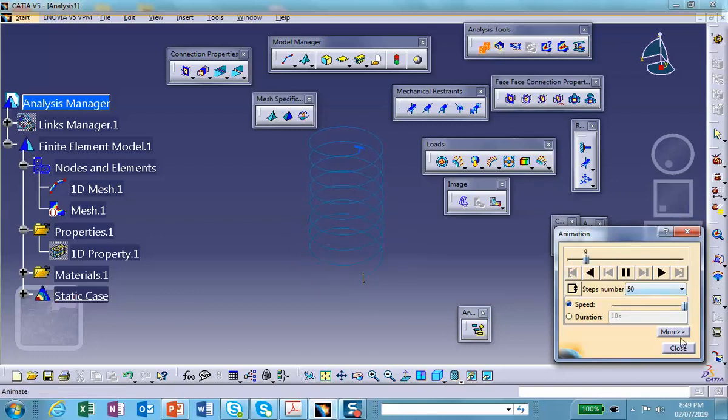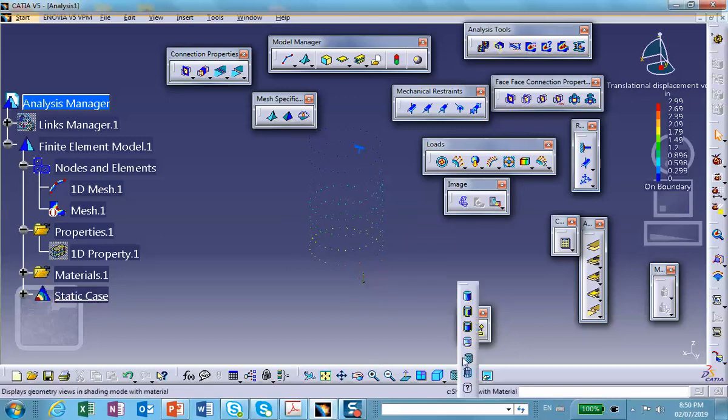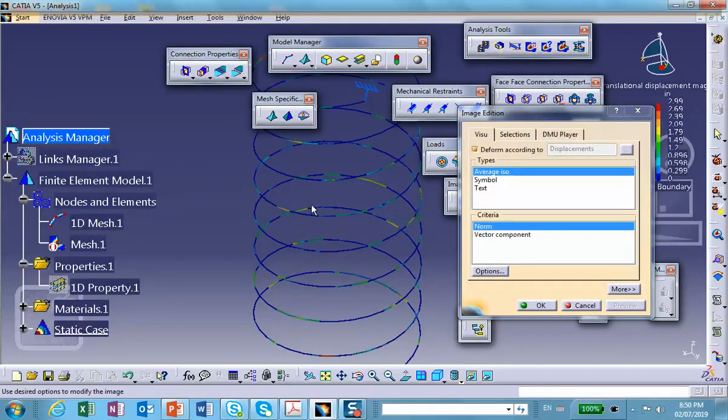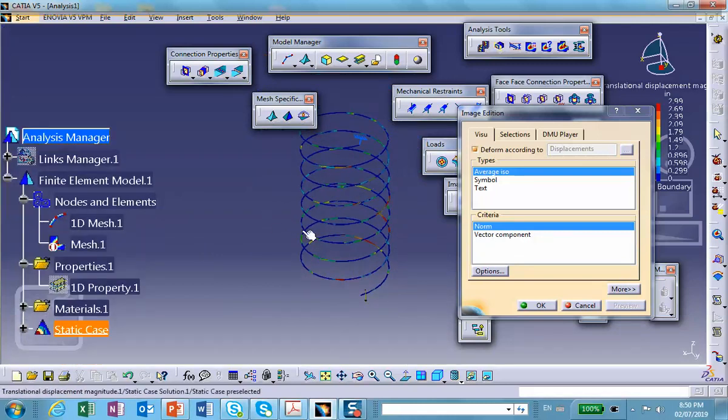But okay, what about numbers? The numbers are right there. This is the actual deformed shape, with the numbers. So double click on it, and I can go here and change it to material shading. Let me double click on this. And look again, my graphics card is a disaster. It doesn't give me the correct colors, but the magnitude of deflection is 2.99, assuming that you trust these.